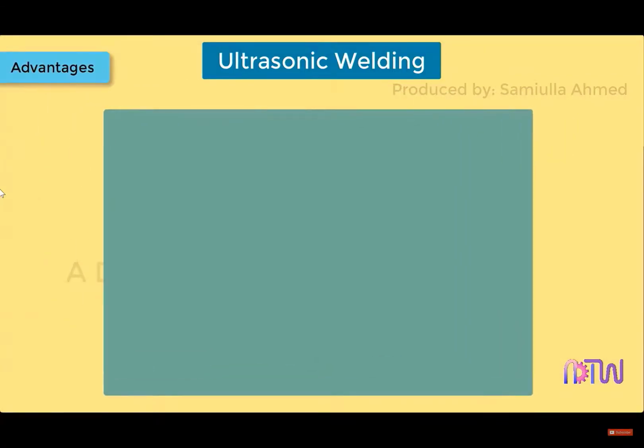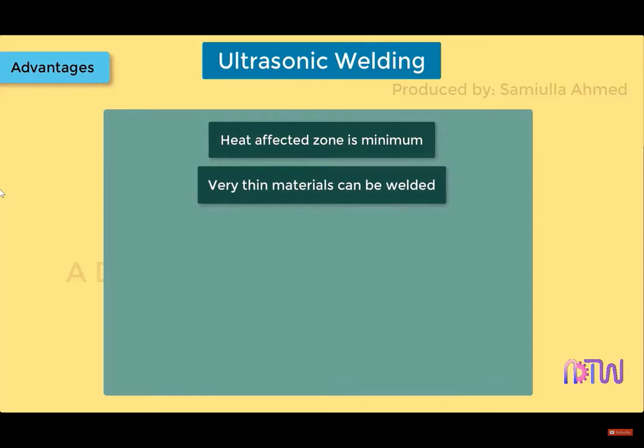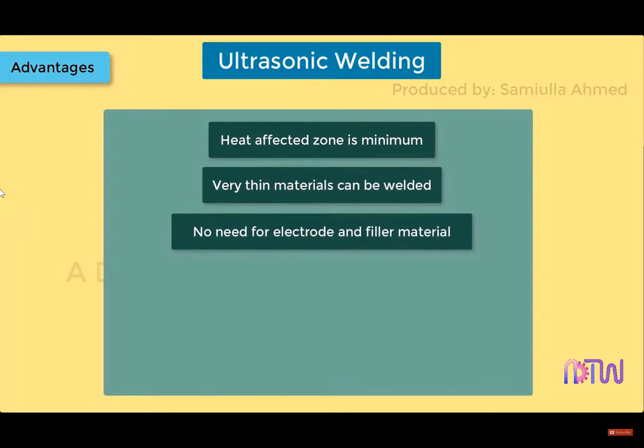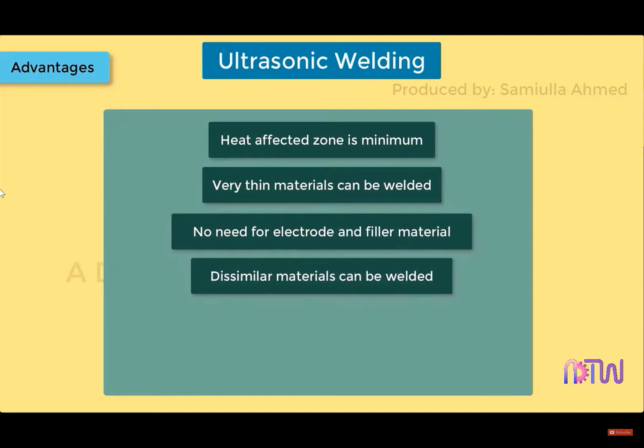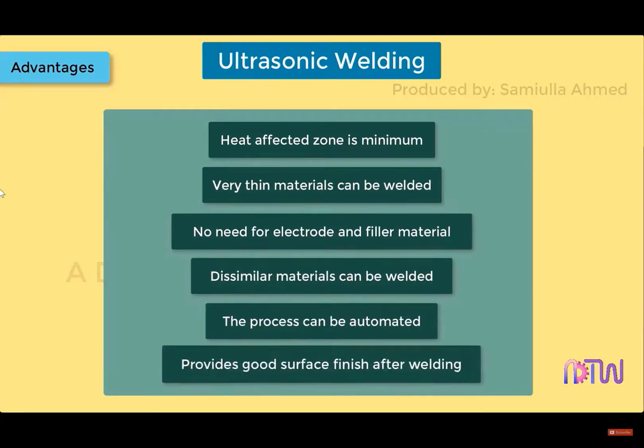Advantages. Since no heat is supplied and no melting occurred, therefore heat affected zone is minimum. Very thin materials can be welded. No need for electrode and filler material. Dissimilar materials can be welded. The process can be automated. Provides good surface finish after welding.